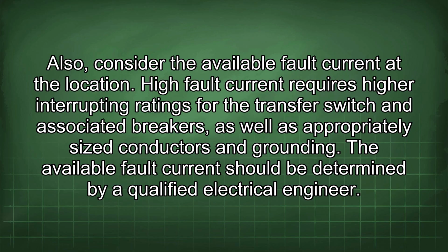Also, consider the available fault current at the location. High fault current requires higher interrupting ratings for the transfer switch and associated breakers, as well as appropriately sized conductors and grounding. The available fault current should be determined by a qualified electrical engineer.